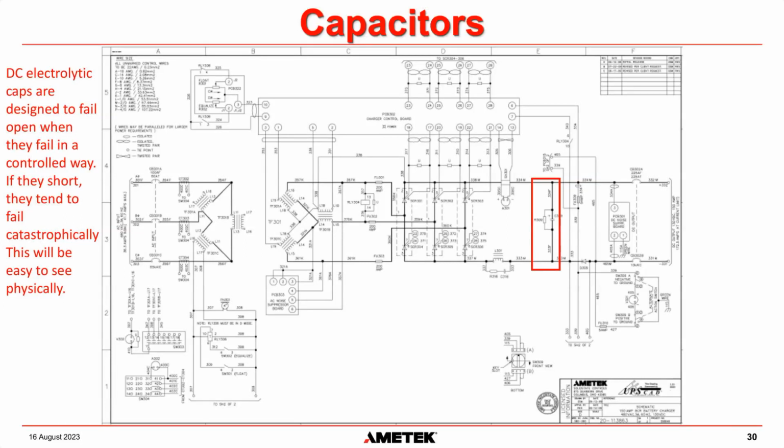But what you want to see is the resistance will start low, and it will start to gradually build up as you keep your probes on the output of the capacitors, on the positive and negative of the capacitors. So if you put the probes on the positive and negative of the capacitors and you don't see that resistance gradually ramping up, then it would tend to be that there's an issue with those capacitors. It's a very simple test.